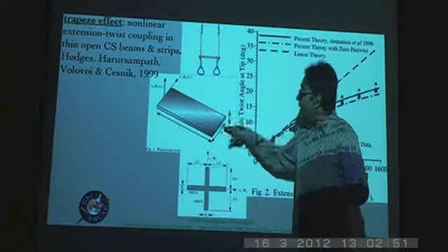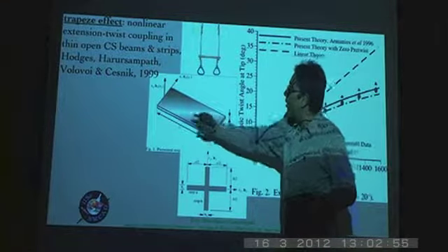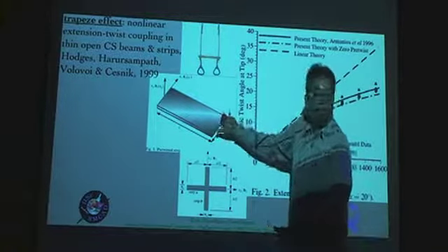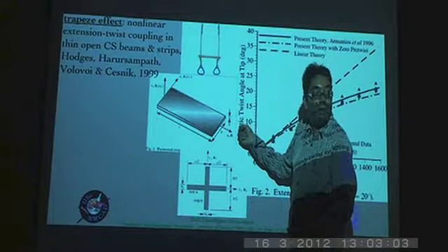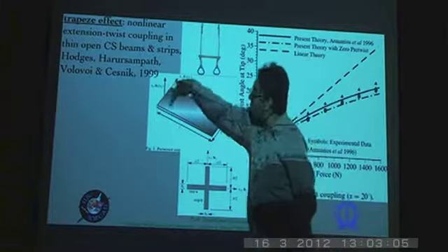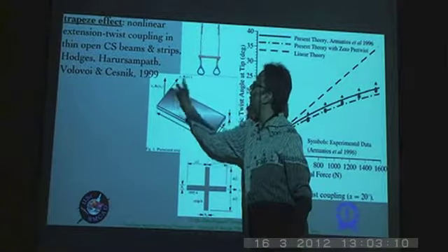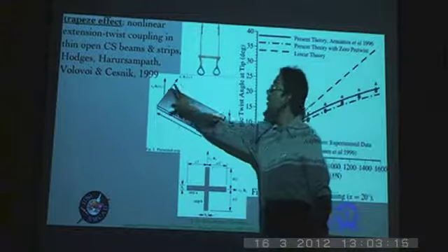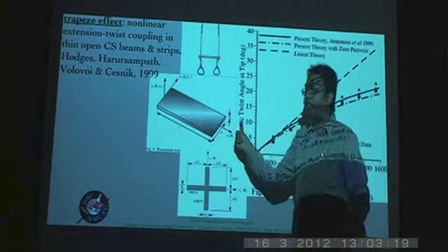So, in a case where it is pre-twisted, for example, if this is a strip, the reason why this kind of lighting is shown is to say that there is some kind of pre-twist. There is no load applied, but even then the angle here and the angle here is different. In other words, your B2 and B3 are functions of x1, because B2 is always along the width, and the width direction changes, and along with it the thickness direction changes as well.